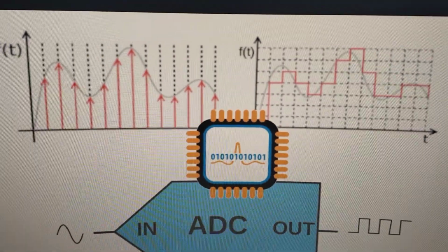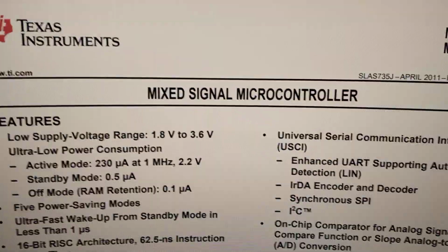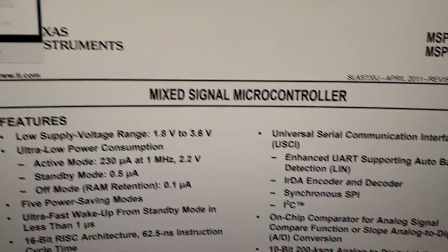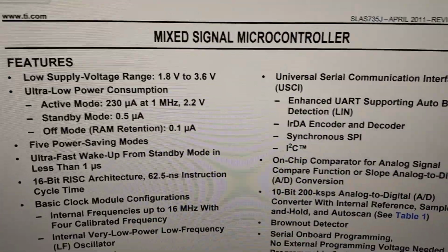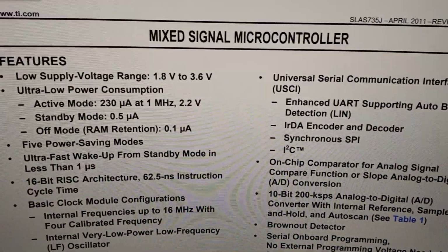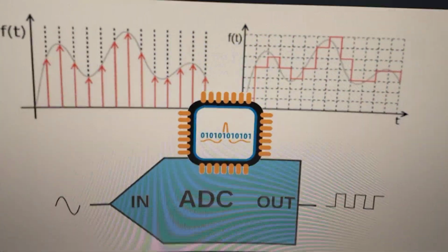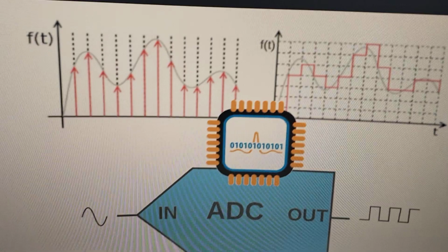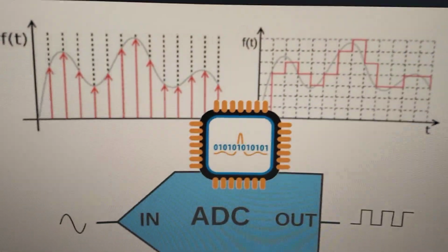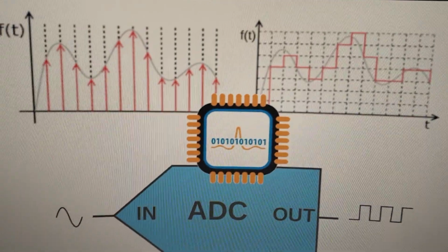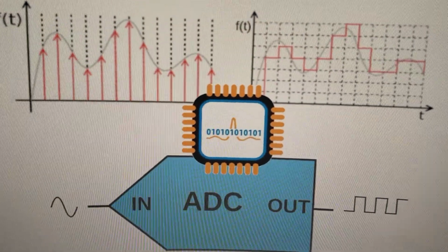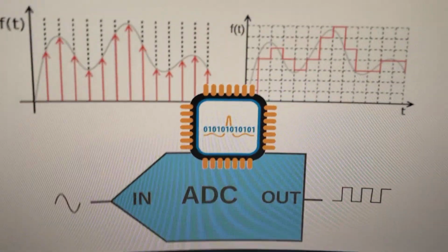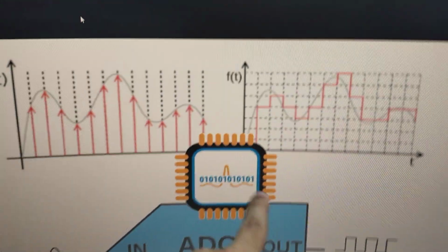And that means your analog signal, and since this is a 3.3 volt microcontroller, that's its maximum range. Of course, you can change the reference depending on what your analog reference is, and your digital value would change. But your 0 to 3.3 volt signal, which you scale down, would get translated to 0 to 1023, and not 1024 because it starts from 0. So 2 power 10 minus 1. That's going to be your digital value, and that's going to be much easier to handle in your code. It's going to give it levels.